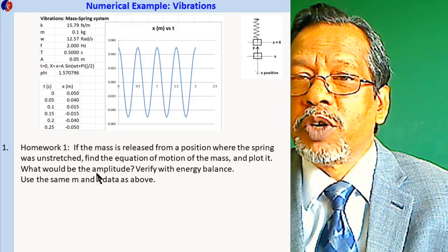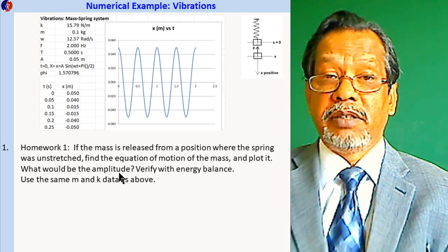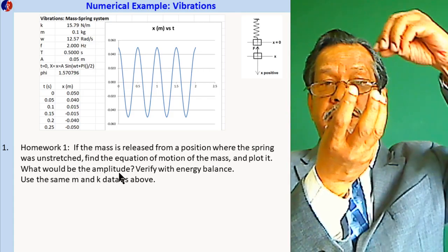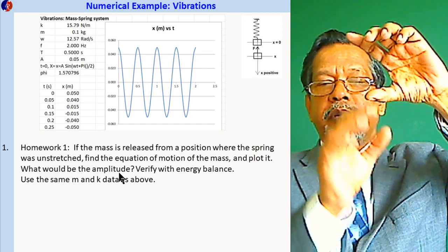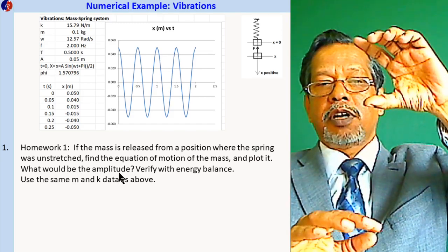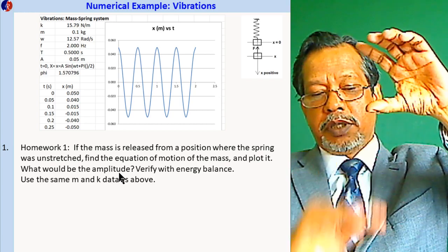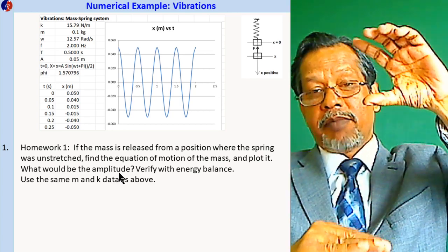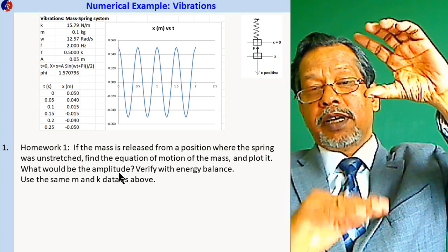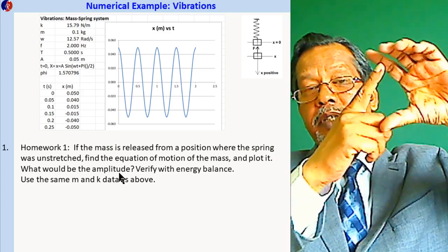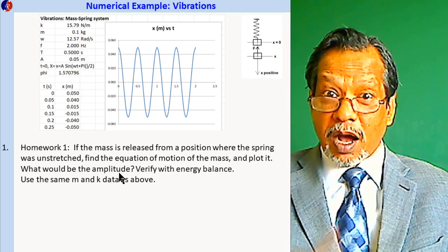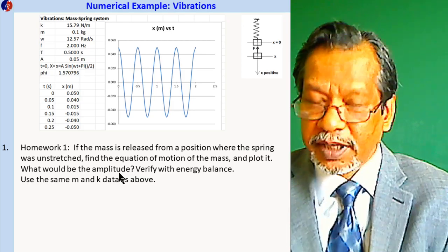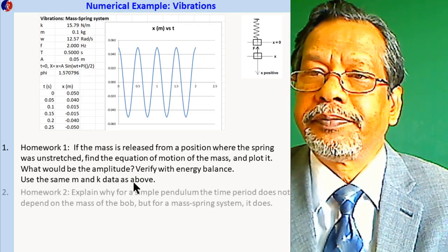Plot it. What would be the amplitude in that case? Okay, there's potential energy of this mass, and then spring had no potential energy. Then when you drop it, it picks up some motion, wants to drop. The entire energy, if it dropped, say maximum dropped to here, all that energy of the mass gets converted into energy of the spring, half kx squared. Okay, let them think about that.